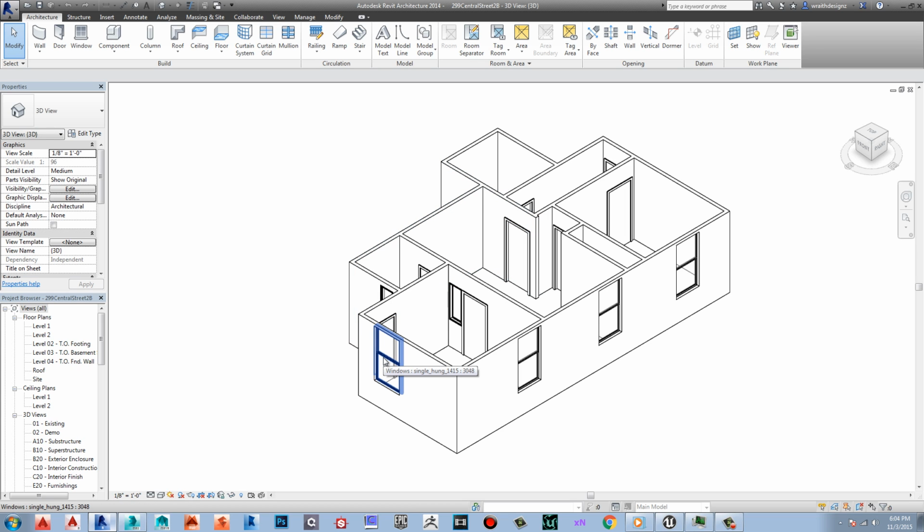I would basically select one of these, delete the rest, center this on the grid, center the pivot point, make sure that in the XYZ axis of the 3ds Max grid it was leveled and centered perfectly. Again, like I said, when you set up your units properly across these programs, they will import to the right size, so you don't have to mess with that. All you do is add your materials, optimize it, and then save it out as FBX file.